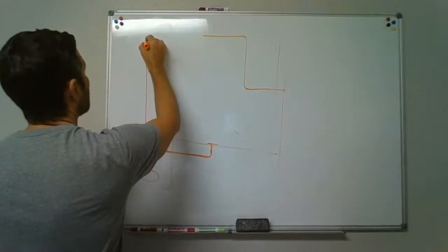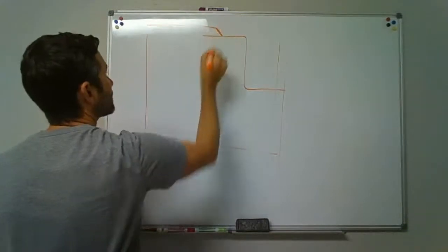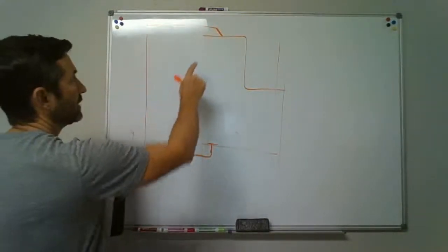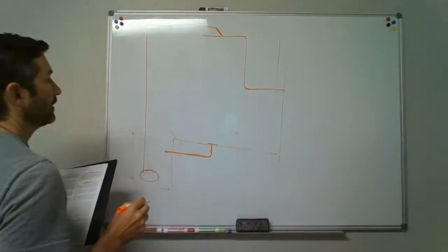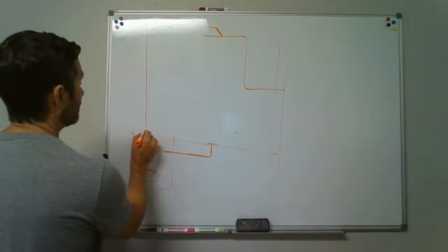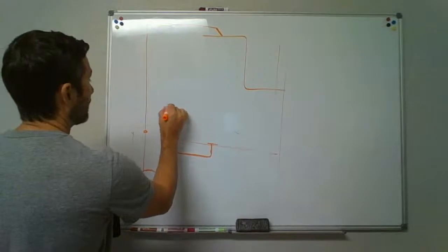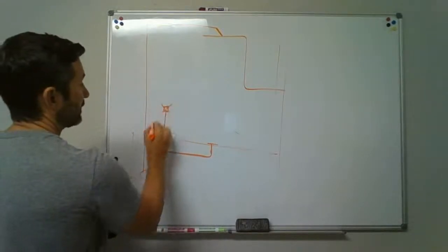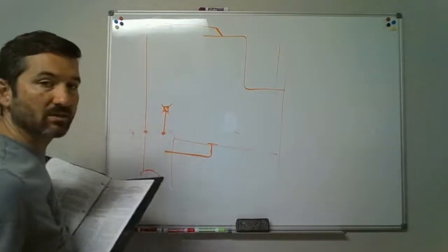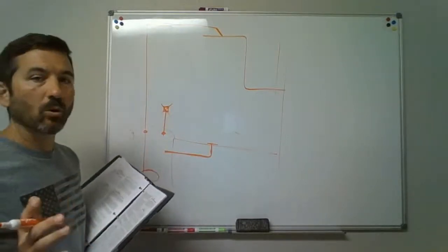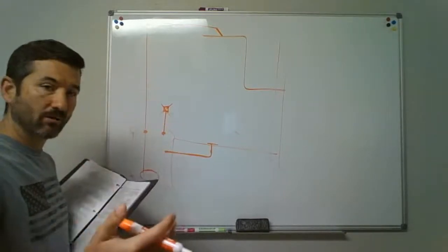Then that can come over. Discharges, remember, through a Y connection to the top of the pipe. This has got to be pressure rated pipe. Discharges in there. And then, oh, this tank also has a little place for a vent to come out of. You've got to vent the tank. We cannot come up and put an air admittance valve. Air admittance valves are not allowed to be used to vent the tank, because an air admittance valve will only allow air to be drawn into the system. It does not allow air to go back out of the system.